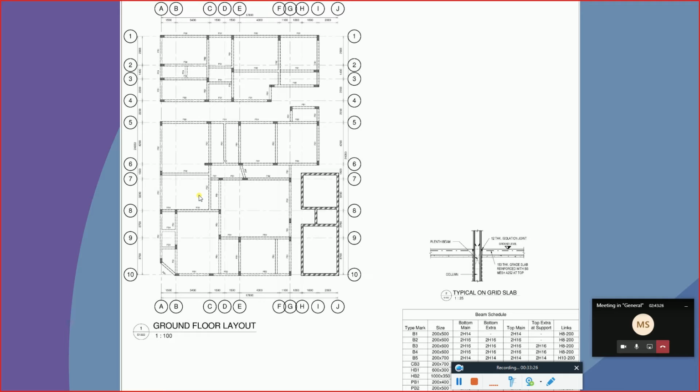The reason is that the ground floor is supported by soil directly. It means that it's not suspended. A suspended floor is a slab or floor that is not supported by the ground, it is only supported by beams, with mostly empty space below. So it's suspended. When it comes to the ground floor, it's not the case. If you remember, for the ground floor, whatever pictures we have shown earlier, the ground floor is laying down exactly on the ground. It has been backfilled, and after the backfill we have the ground floor. It means that all the loading will be taken by the ground.